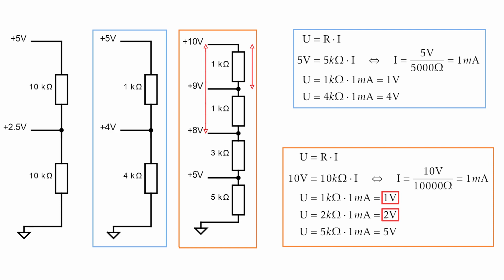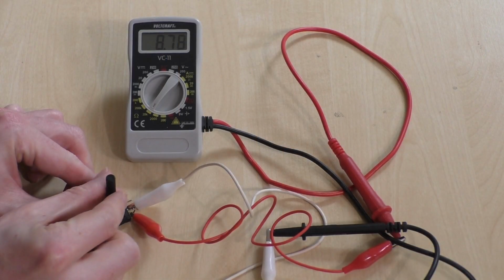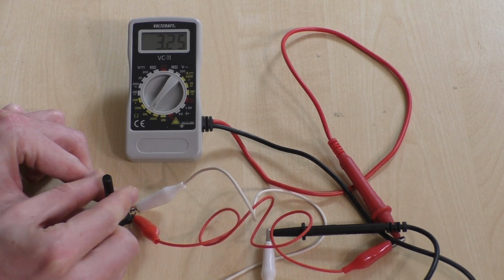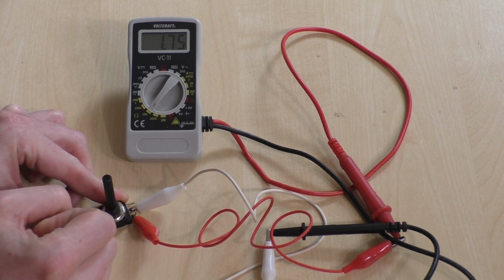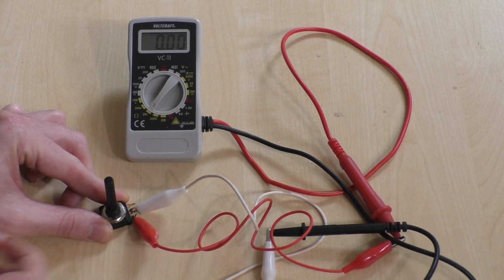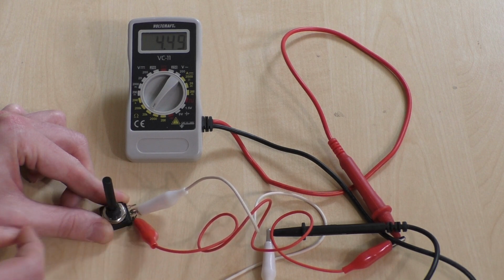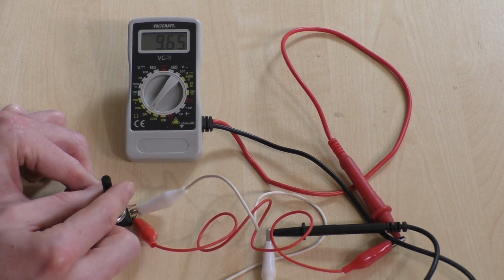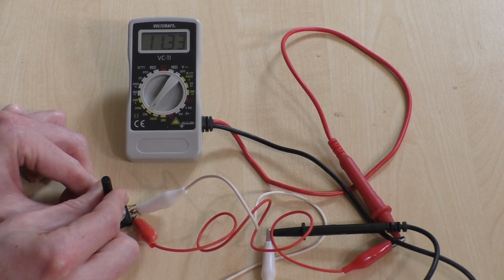How can this concept be used to realize an analog input device? Nothing simpler than that, by using a resistor with variable resistance. That's exactly what these control knobs and radio dials are, resistors that change their resistance depending on their current control state. These parts are called potentiometers. A voltage divider in which one of the resistors is a potentiometer can therefore be used as a sensor that translates physical motion, usually rotation, to an analog voltage. This analog voltage can then be sampled by an AD converter to get a number in digital representation.